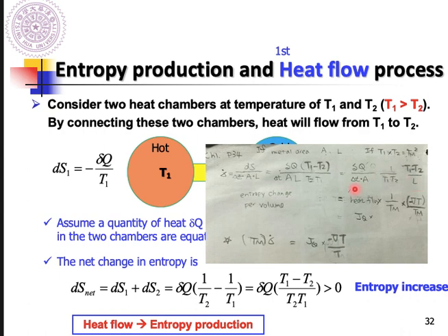Okay, so now what we have is the heat flux times 1 divided by T1 T2. In order to make things simple, I make an assumption, which is that T1 times T2 equals Tm squared. This means I assume there's no big difference between T1 and T2.